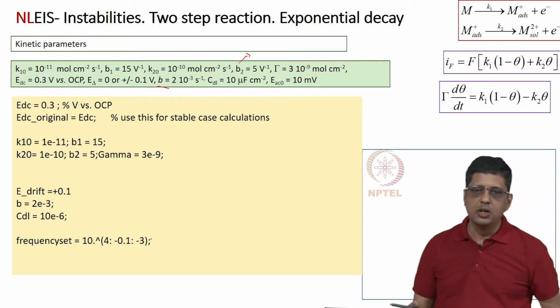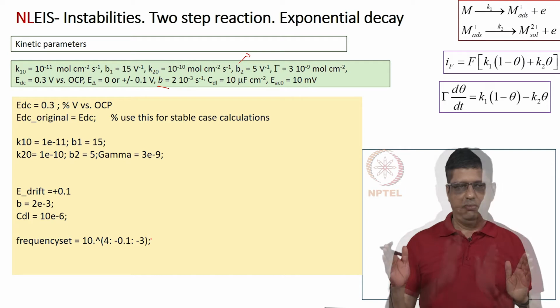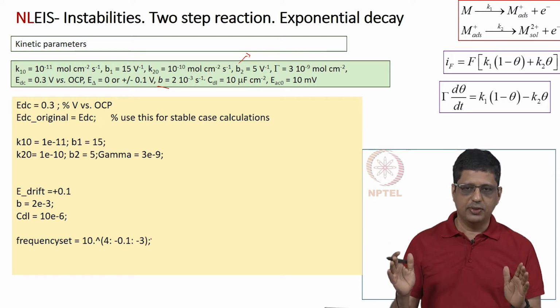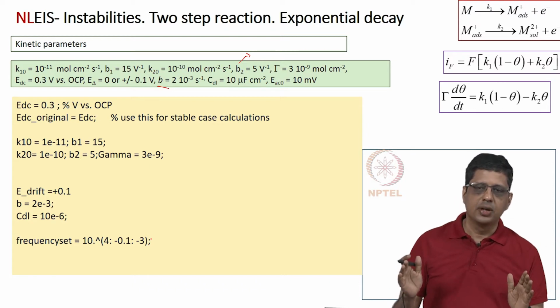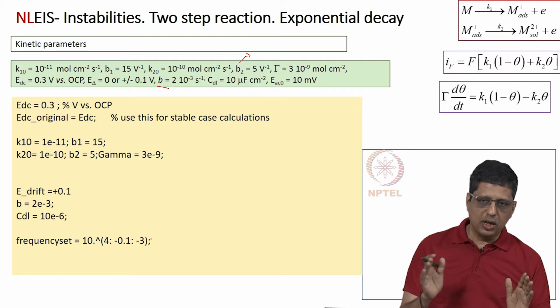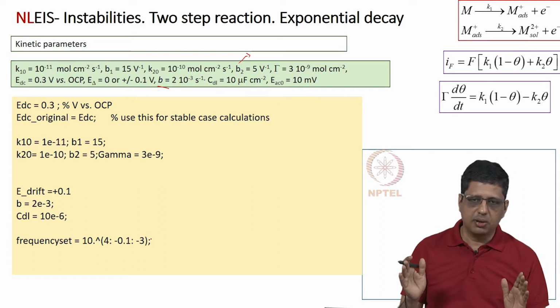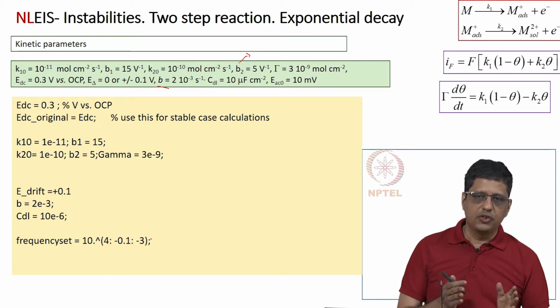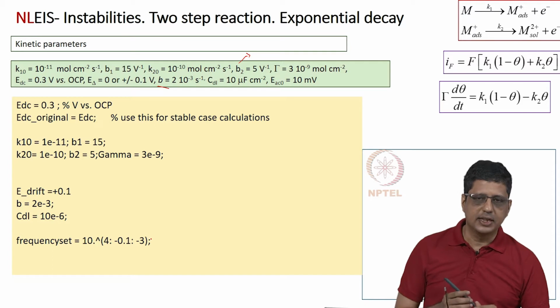So, that is another way. You can have fine intervals for the frequency and coarse intervals for the frequency, and do two sets of measurements. If they are more or less overlapping, then you can probably say that drift is not that significant within the experimental level. If they are quite different, then this is one thing you need to consider.